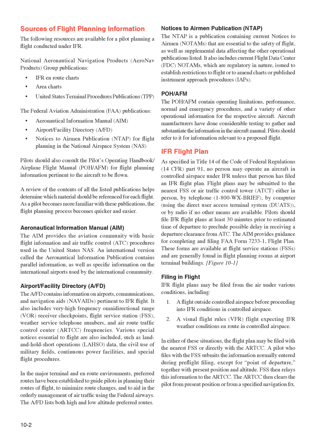Sources of flight planning information. The following resources are available for a pilot planning a flight conducted under IFR. National Aeronautical Navigation Products, Aeronav Products, Group Publications: IFR En Route Charts, Area Charts, United States Terminal Procedures Publications, TPP. The Federal Aviation Administration, FAA, Publications: Aeronautical Information Manual, AIM, Airport/Facility Directory, A/FD, Notices to Airmen Publication, NTAP, for flight planning in the National Airspace System,